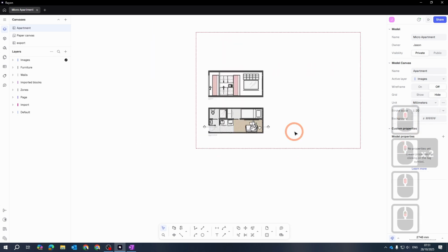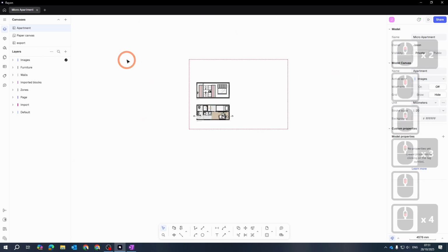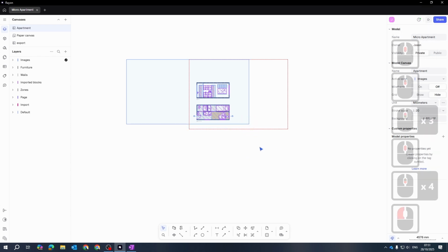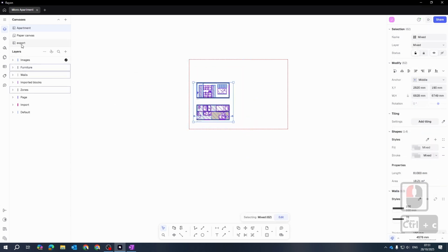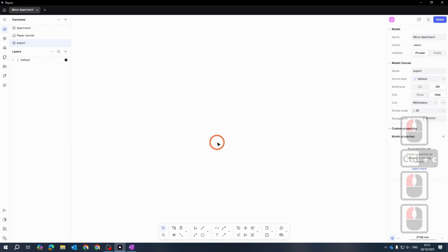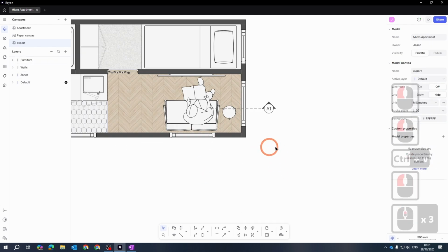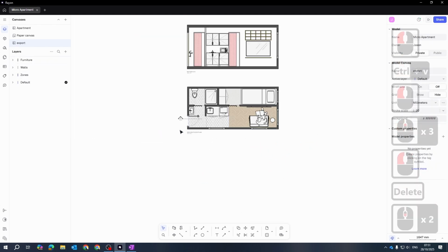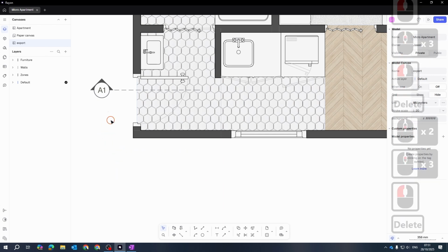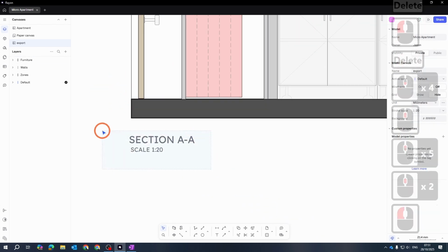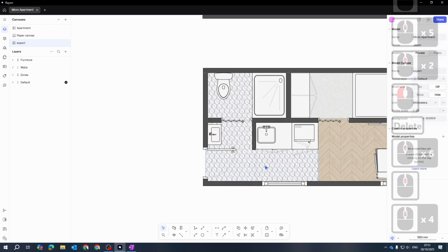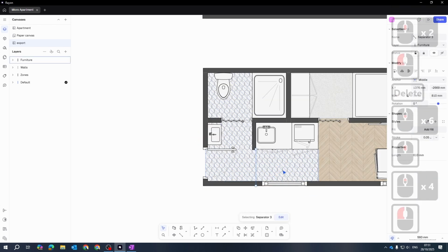Okay, so the first thing you need to do is copy everything. Control C, and if you look at my keystrokes, Control V. So I'm going to paste everything and then delete all the annotation objects. You could also go and delete the fills and the zones if you don't want that information to come through. So like these zones and these dividing lines for the zones.